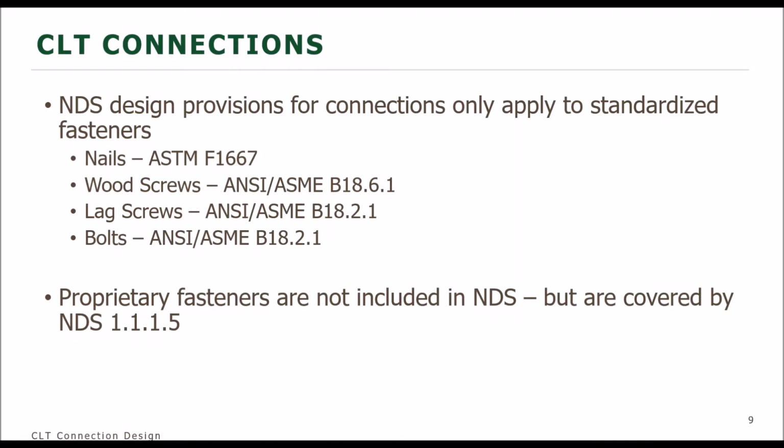They are covered by some language in NDS 1.1.1.5, which states you are permitted to use materials that are beyond the scope of the NDS. However, they would need to be approved by your authority having jurisdiction, obviously. And you would need to get the installation and the calculation and design values and things like that.